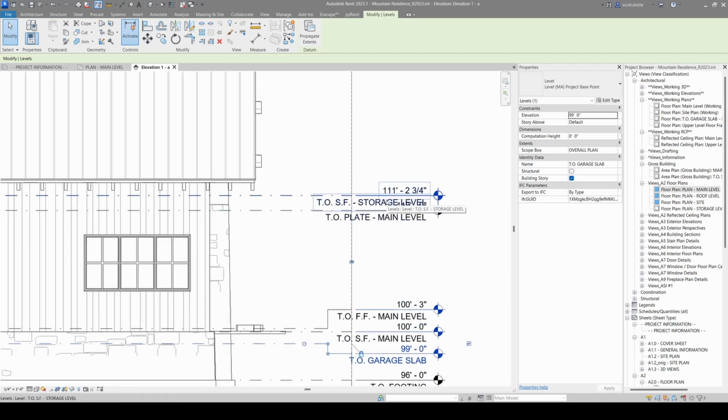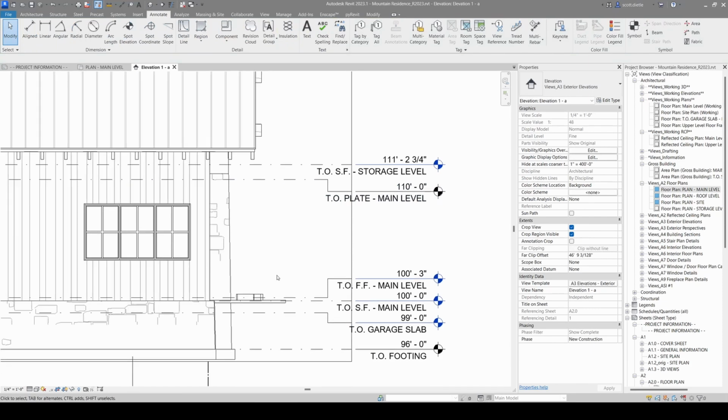This one's overlapping. Here's another tip. Revit automatically adds, when you click the add elbow, it drops it below the current position. So a way to cheat this so you're not always clicking and dragging back up above is to click the elbow and let it drop down and then move it over. It's a very nice, easy, quick way to do it.